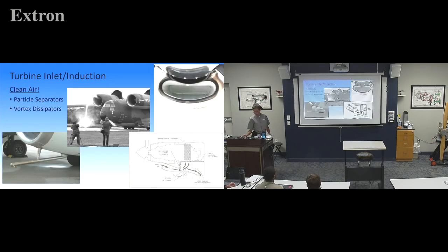So, I think y'all had a second to look at this. I was going to ask you this one. Do we put filters, or very often do we put screens on turbine aircraft? No. Right. Because why would we not put inlet screens on turbofans? Too much restriction. What's some other things?